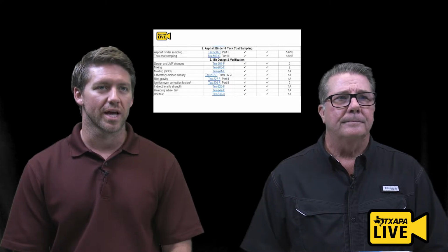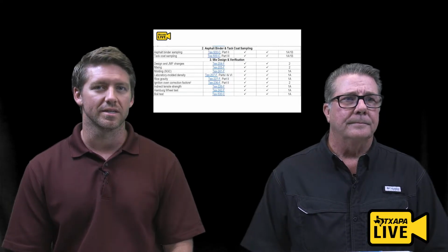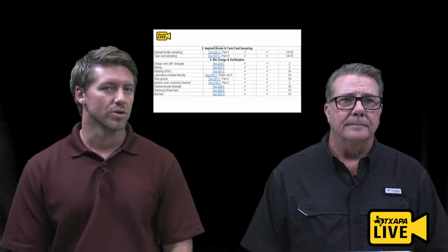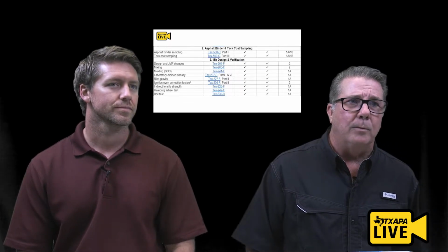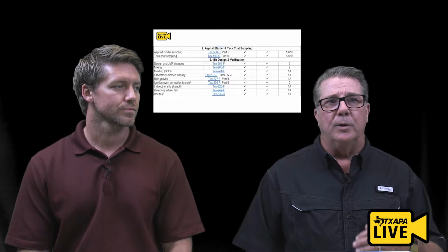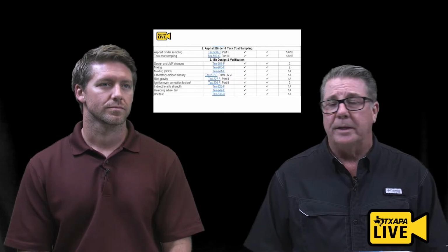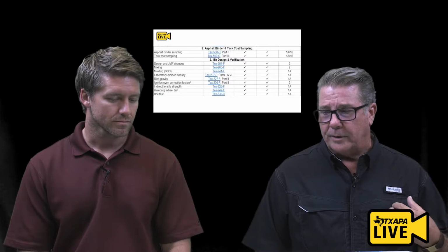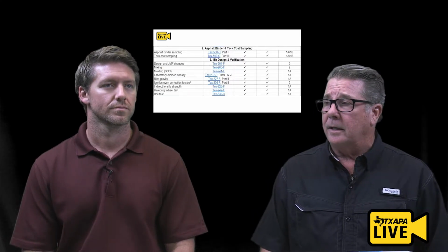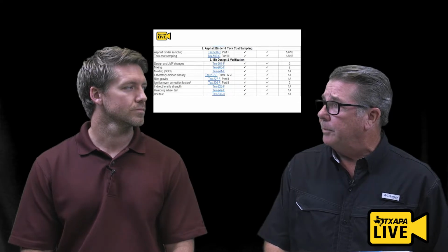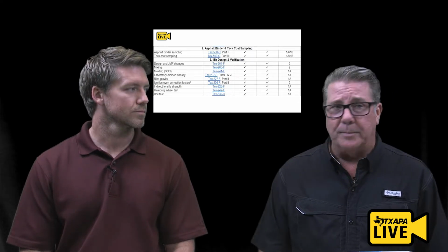So you can use that throughout the entire state. MTD does have 6 of those machines, so if you need testing, MTD can run it. Great. And again, when we're talking about sampling and who's responsible for it, the production sampling is done by the contractor doing QC, and we're going to get into that a little bit later on, and then TxDOT's QA, which is going to be quality assurance, quality acceptance.